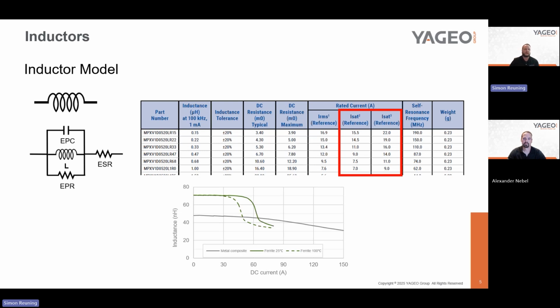But that's not all. As the power supply is going to run, you're going to have some losses in that core, and that's going to cause self-heating. So that means that core material is actually going to run significantly warmer than you might expect. And if you don't consider that in your design, you could get into a thermal runaway situation where you start getting hotter and hotter because now your inductance is going to drop because you're running into this soft saturation of your transformer.